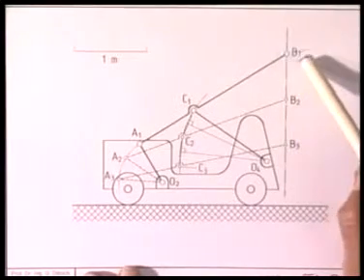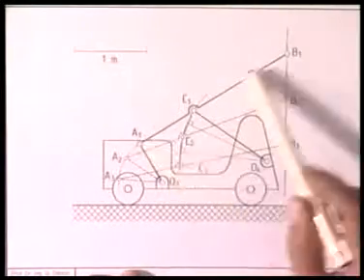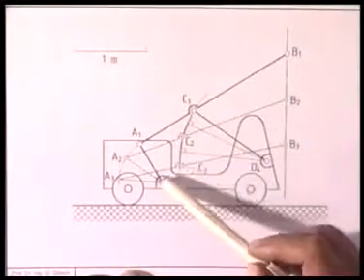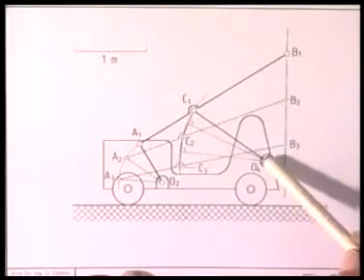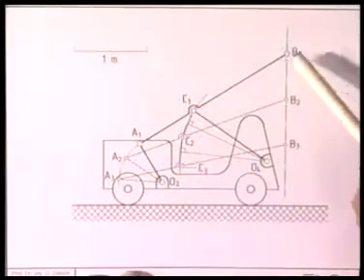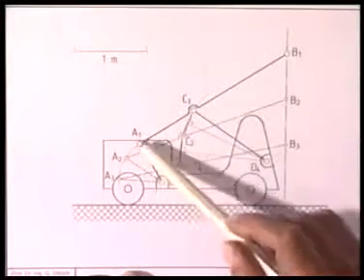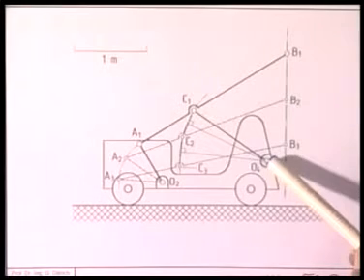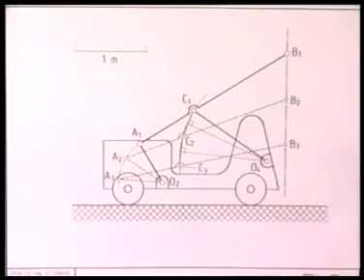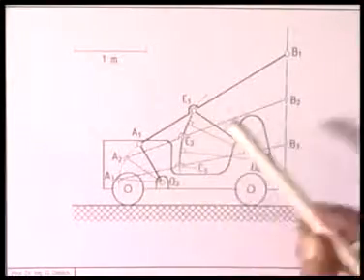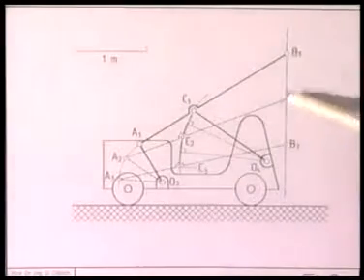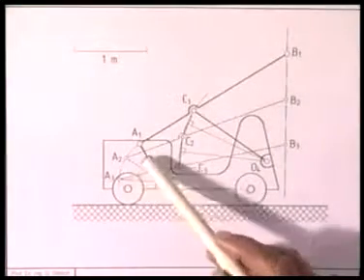Now I remove the slider at B1 and treat this link AB as the coupler of a 4-bar link, namely O2 A C O4, and B is the coupler point of this 4-bar link O2 A C O4. Our objective is, how do I determine the correct location of O4, so that when this 4-bar linkage is moved, this point B1 will automatically pass through B1, B2, B3, and maintaining the coordination with the input movement.